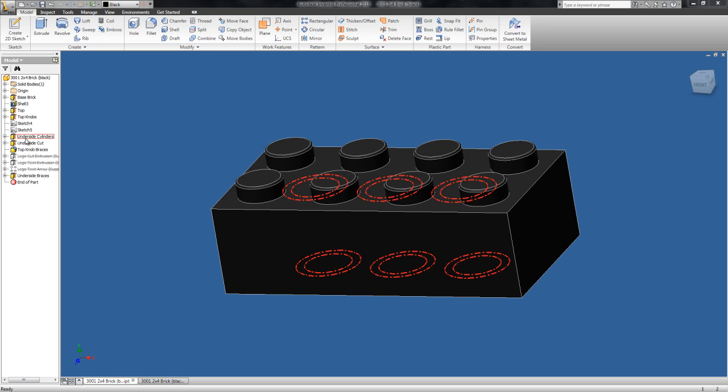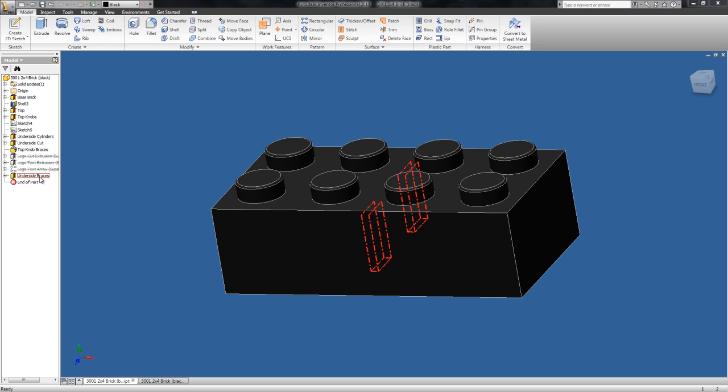we do, we can name them. So they don't have to be extrusion 1, extrusion 2, fillet 1 like I've been doing before. For complex pieces, you may want to have named operations. It's just good practice, because then you can look down if you want to modify. Let's say you want to modify this. You don't have to figure out, okay, which operation is that. You can just say, oh, top knobs. That's what that is. So we can modify it.